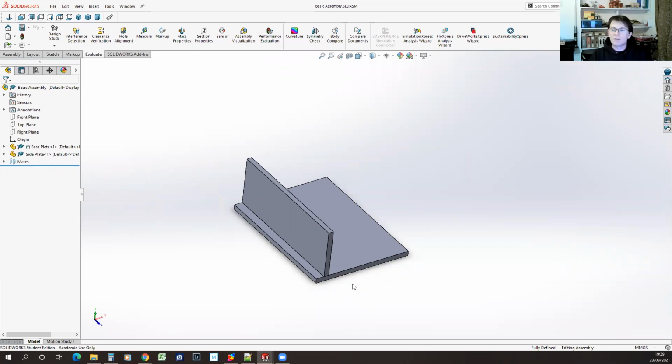Everything in CAD is a perfect view of the world, and then the reality, when you actually try and make something, you find that your 3mm thick acrylic is not actually 3mm, but has a tolerance associated with it. And I'm going to go over some of the tips and tricks that I use to avoid having to do a lot of reworking when I want to make adjustments to the model.